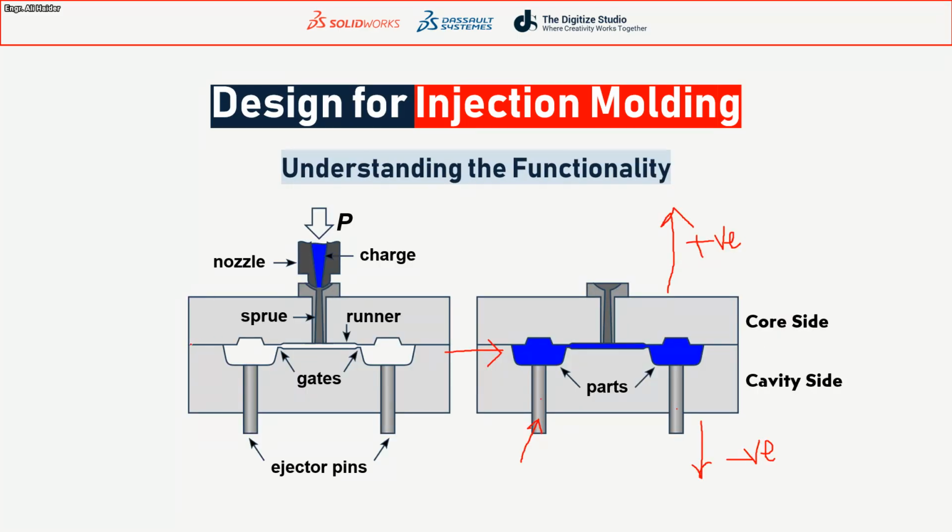And then we have the parting line. By parting line we mean the line that separates the core and the cavity. This is called the parting line, this horizontal and vertical line and downwards. The parting line again should be on the edges, because when there is a misplacement in here, this top line and the bottom line will not be perfectly aligned with each other in actual manufacturing.